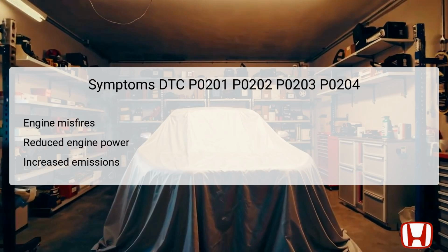The symptoms that may accompany these DTCs are critically important for diagnosis. Engine misfires are often the first noticeable issue, which occurs when a cylinder does not fire correctly due to a lack of fuel. This can lead to a rough idling condition and decreased performance during acceleration.